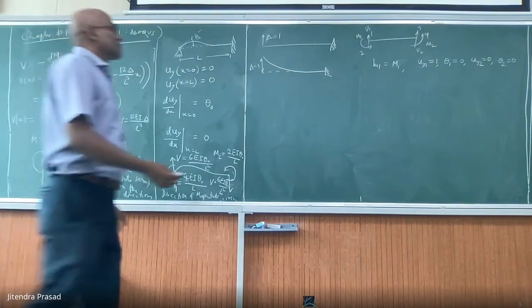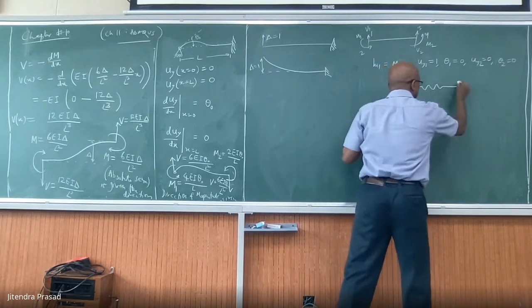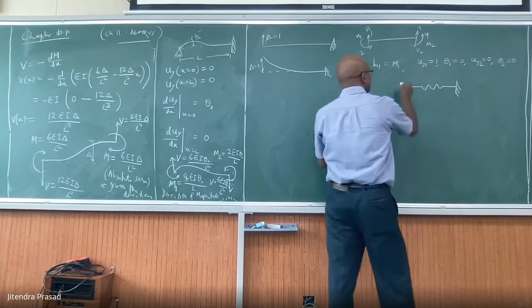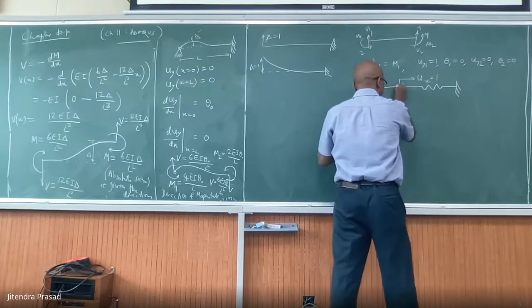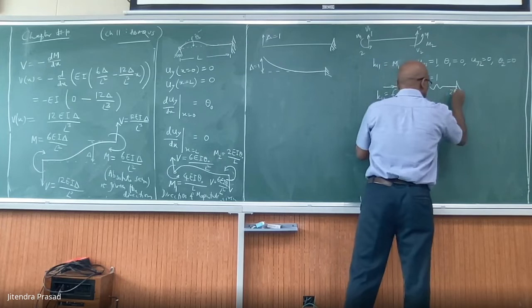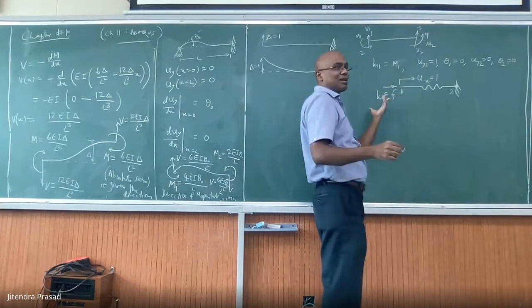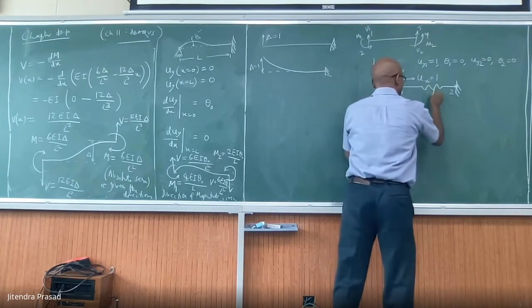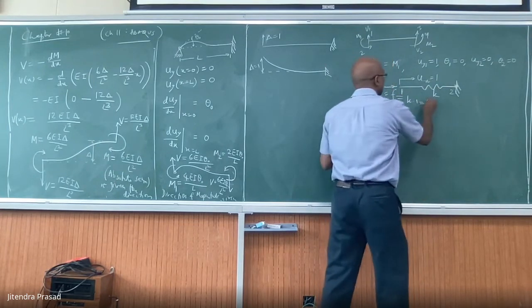This is how you remember it, like we had a spring and we stop here, apply U, X equal to 1, and then measure the force. So K11 was when the other degrees of freedom were constant, you gave a displacement to degree of freedom 1, and you measured the force. If this is K, F is equal to K times 1, which is K.